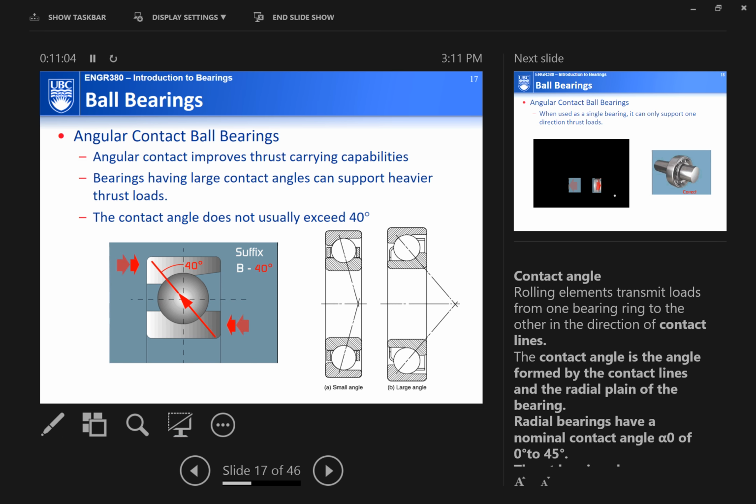And this one here, a couple of examples of ball bearings. This is called an angular contact ball bearing. So what the angular contact essentially is, the inner ring is essentially like a deep groove ball bearing. It's the same thing. You have a groove, you have a raceway, you have balls here, and the outer ring here slightly looks different, right?